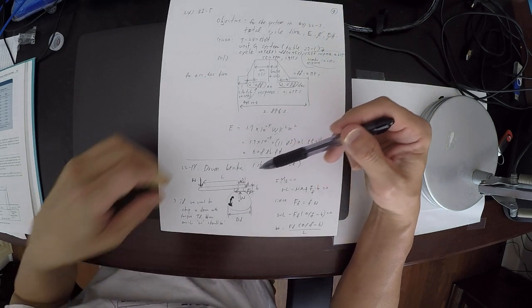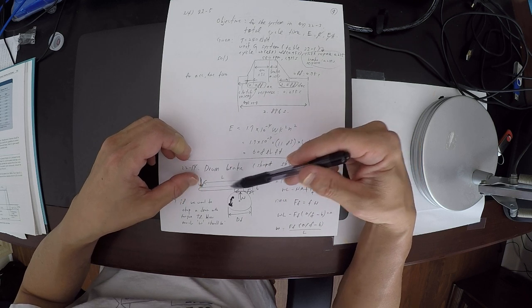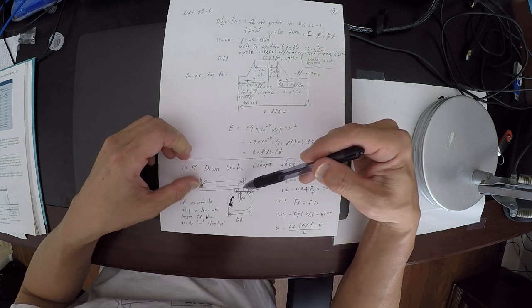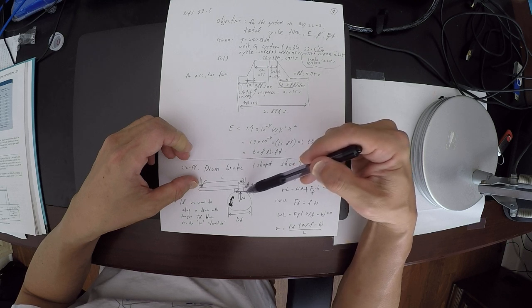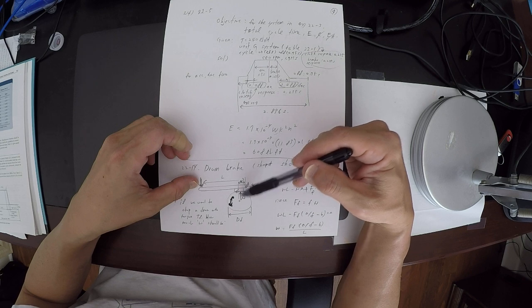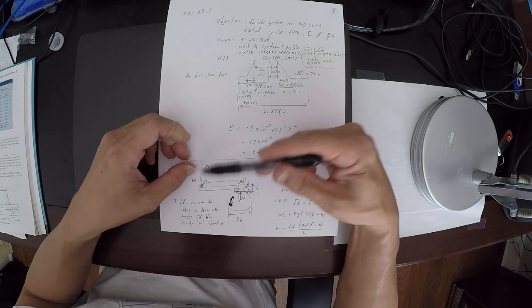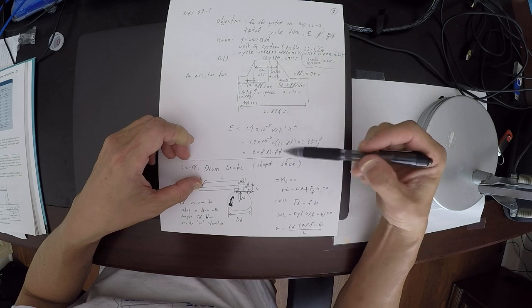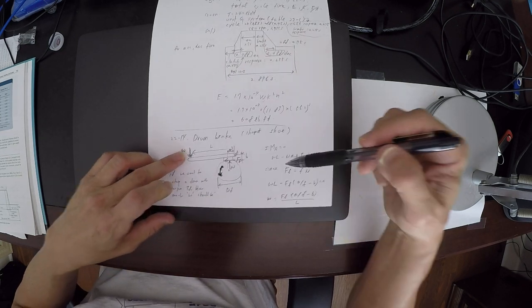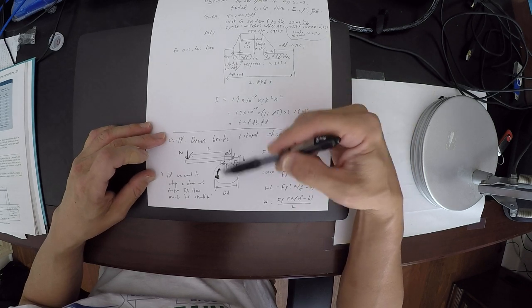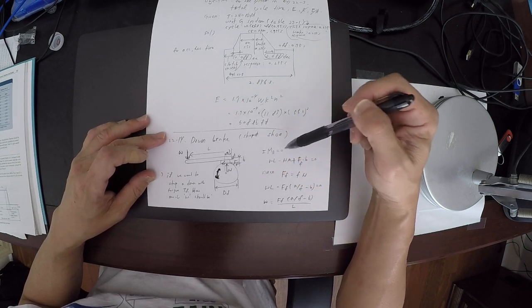where you apply the force with a lever, so that this force will be amplified by the leverage effect to cause the friction right here. And then this friction actually again is a function of the normal force. The normal force is a function of the force that you apply. So if you want to calculate the W that you need to apply to stop this, assuming that everything is in static equilibrium,